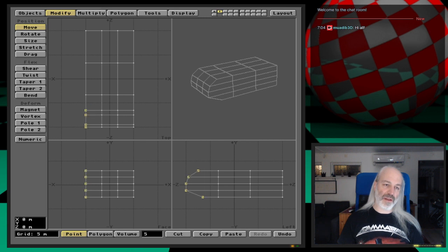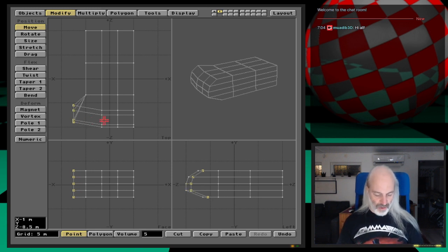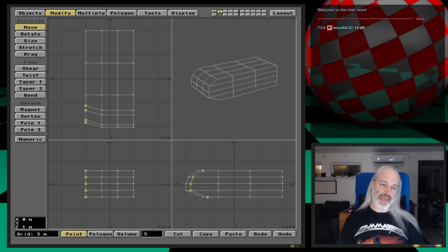While if I do it without pressing the control key, I am having the 500 millimeter increment as well. Okay, so using control, it actually locks the cursor to do fine movements along the first axis, but it gets into coarse mode for the other axis.